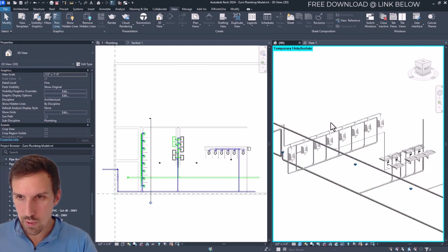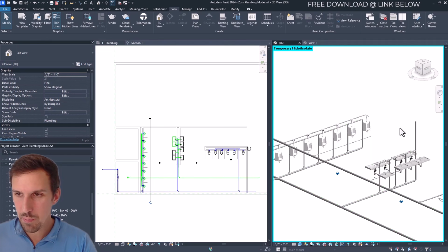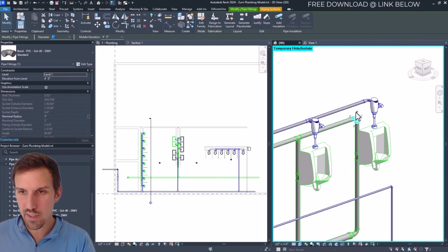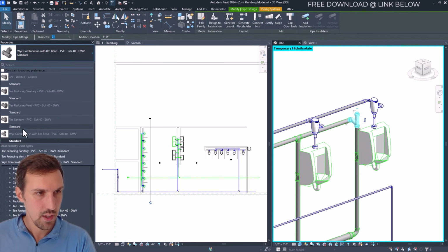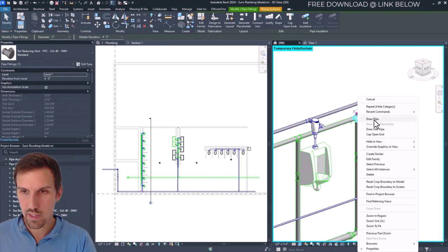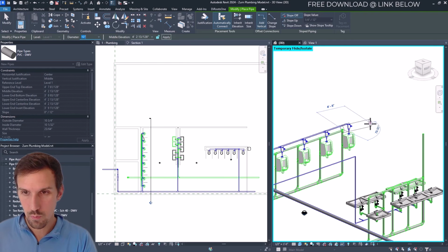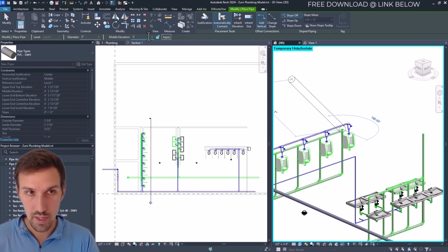So there's a lot of, oh, we forgot our vent piping. So it doesn't really matter where you put the vent piping. Since I already have one over here, I'm probably going to put it at the end right here. So I'm just going to click this and click this little plus. I will change this to a T reducing vent. That's fine. We'll right click, draw a pipe, and then we'll draw it up to 10 feet. And whoa, that's the diameter. Whoops. Let's draw it up to 10 feet.